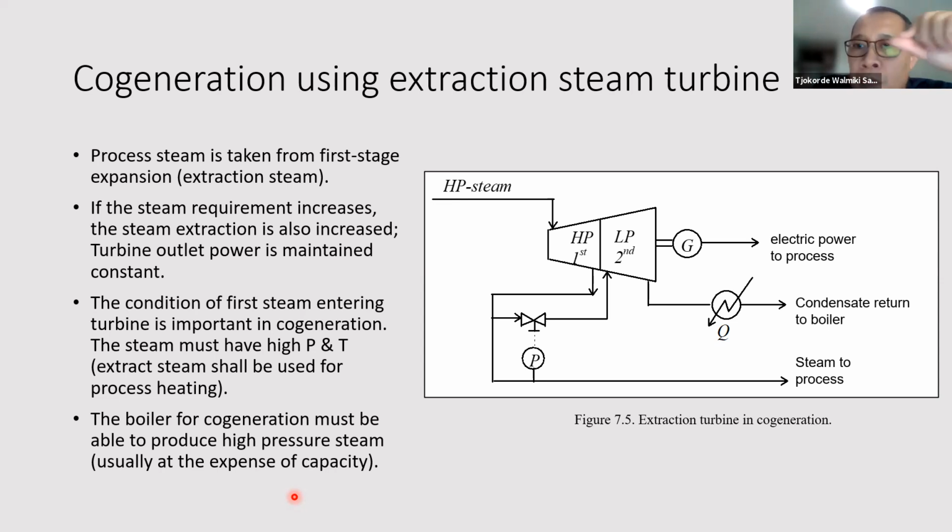If you have a process heating task, you need to be aware that if this is your target process temperature, your heating media has to be higher. It has to have a certain delta T to ensure good heat transfer. And if your heat transfer media is steam, remember, steam needs to be transported in a superheated state, not in a saturated state. Yes, when it enters the heat exchanger, when it's about to do its heating job, then it has to be de-superheated. That is correct.